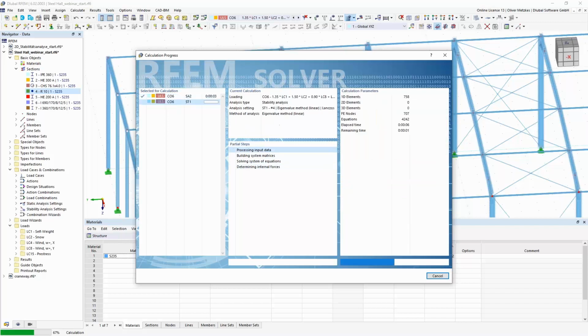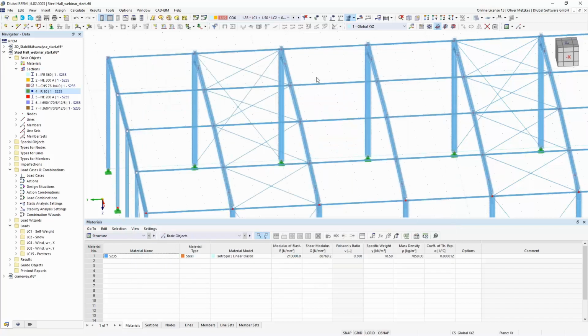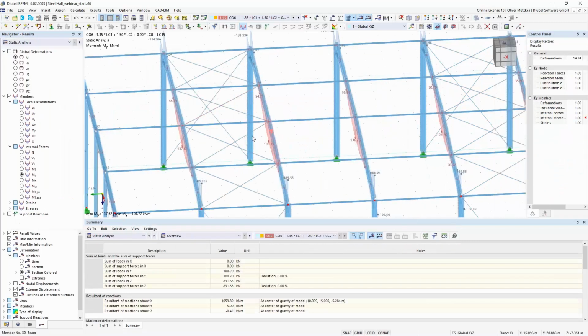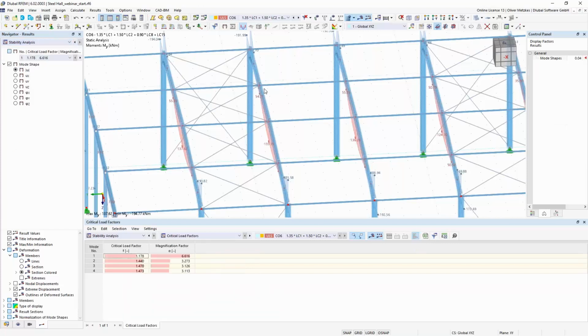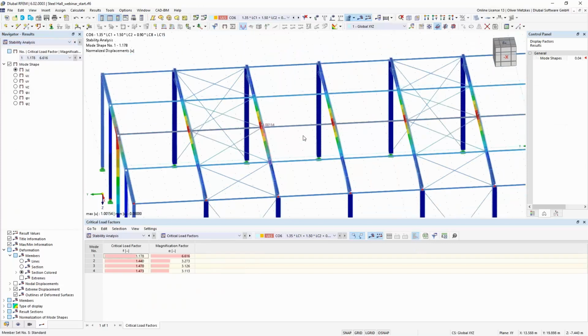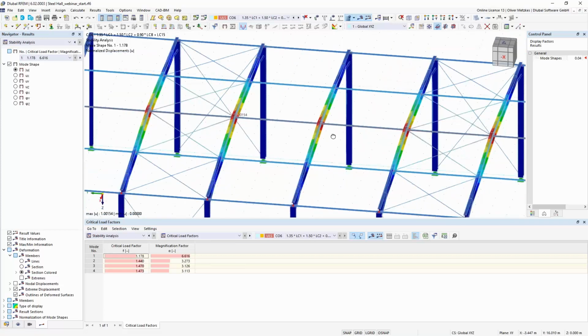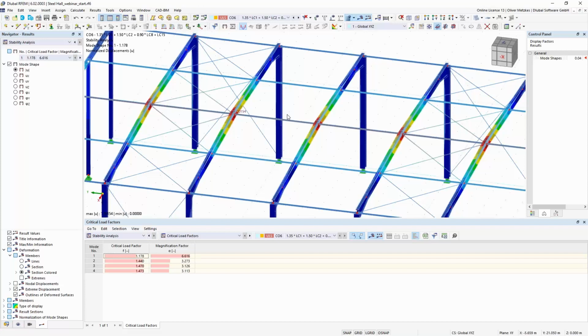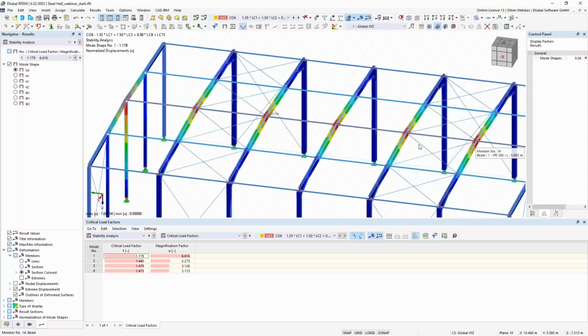So in this load combination number 6, before it was lateral torsional buckling between the fixations of the bracing. But now we have a lower stiffness, and it's not stiff enough to prevent the flexural buckling of all the frames. So now we have a lateral torsional buckling mode shape with critical load factor 1.1. The first one is now the most critical one, not between the bracing fixations, because the stiffness is too low now. So we will have this global lateral torsional buckling here.